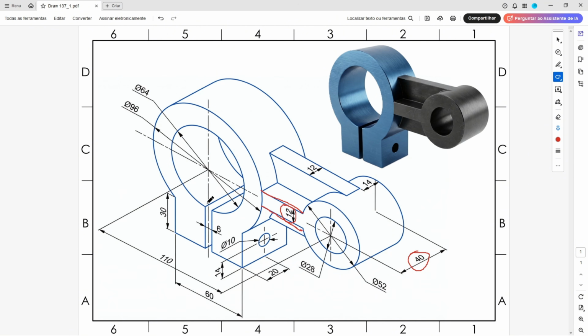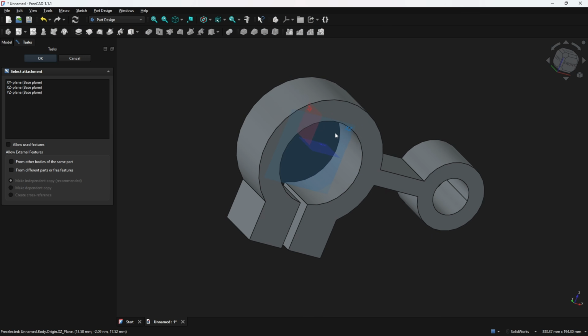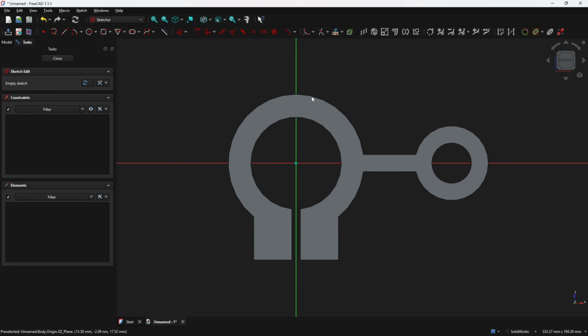And now we will select the front plane again and we will make this sketch here. Look at this. An arc here, another line and another arc here, okay? So to create this, select the sketch and select the front plane. And here, go to external projection and select this arc here and select this circle here. Activate the toggle section view, okay?